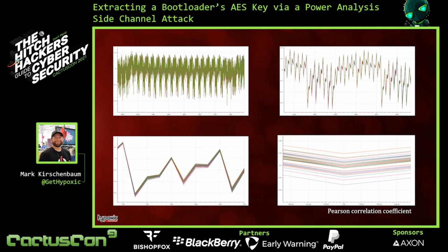That's really neat and all, but how do we automate this? Well, in order to show you how we automate this, I first want to show you what we're working on. To the left here is basically our power trace. I'm going to grab a pointer. So this is our power trace of probably about 50 power traces. They're all stacked on top of each other. But what you can make out is the 16 inverse substitution byte blocks here. There's 16 of these little pulses all along.